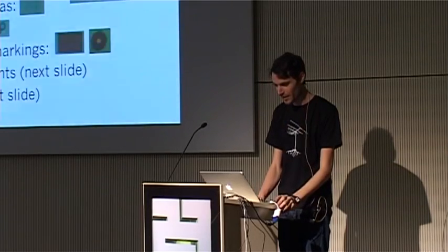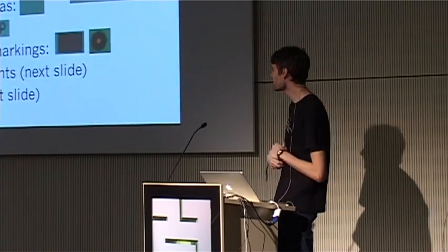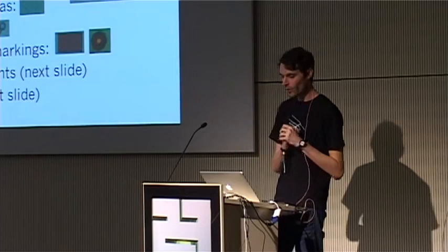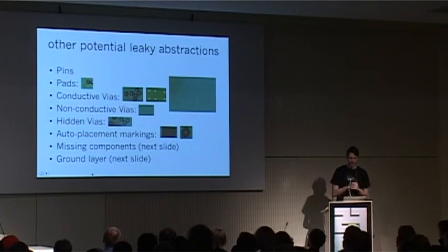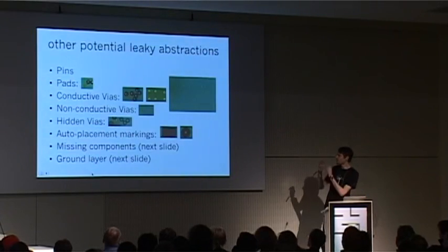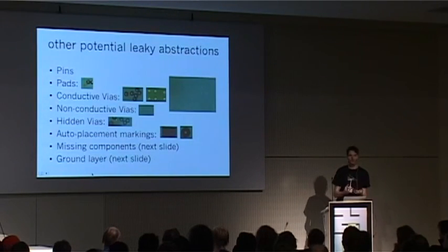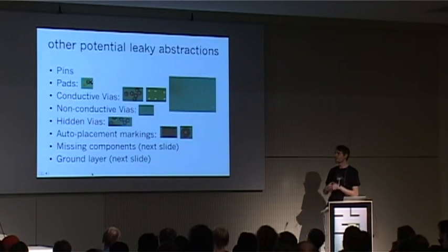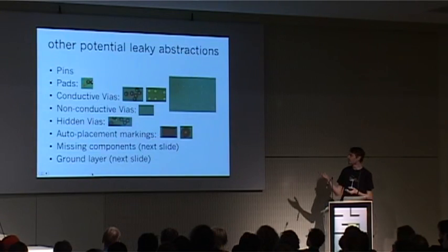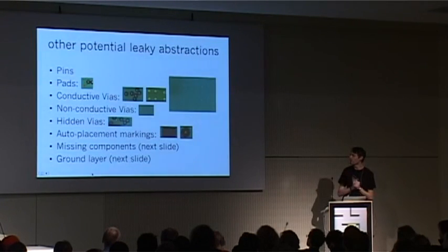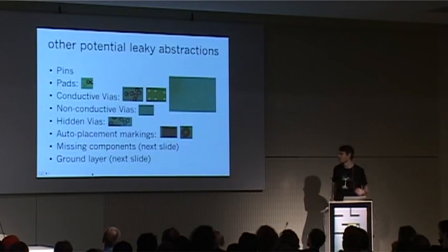Okay, so I just wanted to look at some other things that I noticed while looking at PCBs. So these are other areas that you might not think are interesting to look at, but actually looking at them, each arrangement and the way in which they're arranged and the way they look is important, or it gives some clues either to the developer or the manufacturing process. And in particular, some things you can look at are pads. So the pads you see there, one with a circle around it is not grounded, so it connects to something, and the one without is grounded in pretty much every case.